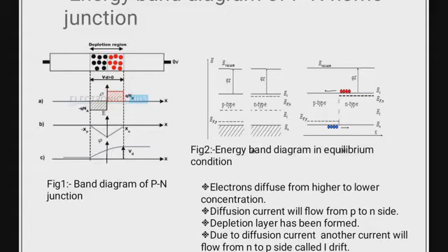That means if we take a derivative with respect to distance x, then we get dE_F/dx equal to 0, where E_F is basically the Fermi energy level in this semiconductor diode, and E_F is independent of x if the derivative is 0. That means the Fermi level is constant. The Fermi level is constant.